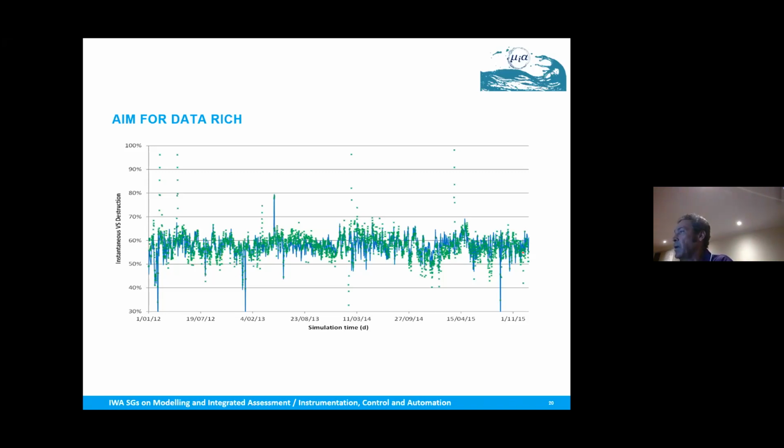So I was able to say to them, this is your apparent degradability, this is your hydrolysis rate coefficient. I set the hydrolysis rate for carbohydrates, proteins, and lipids to all be the same value, in this case about 0.3 per day. And I can say there's no change over time, and here are your values, here's what your performance will be at 16 days versus 18 days versus 20 days, and generate performance curves. That's a far more powerful way to do design and analysis than the classic method of here's some assumed performance curves. These are actual performance curves based on their sludge. This was a mix of primary and activated sludge.